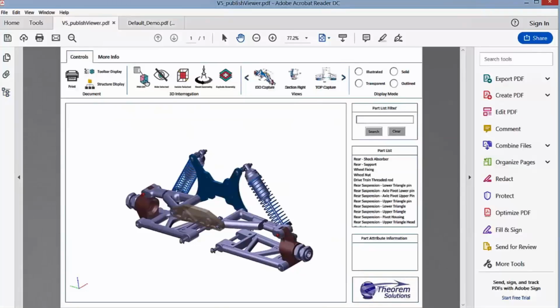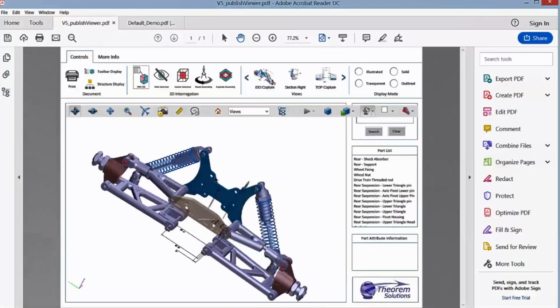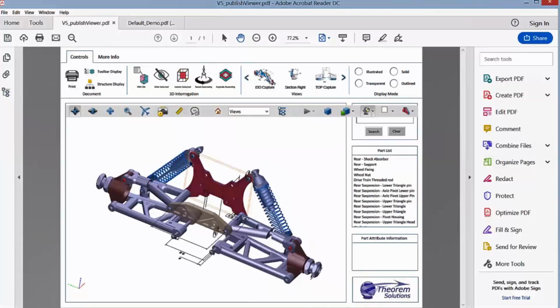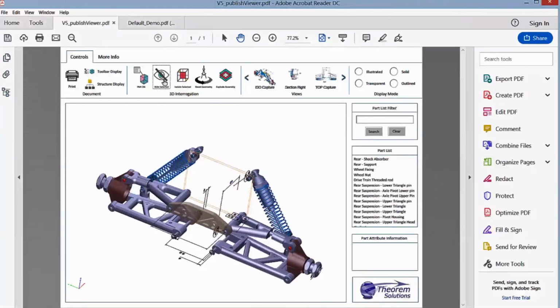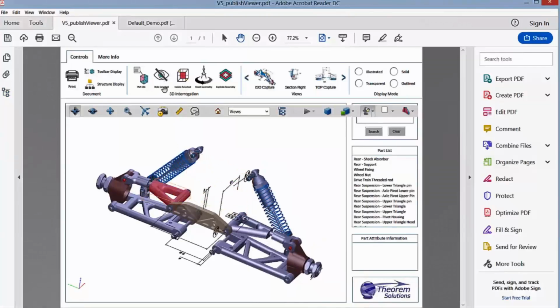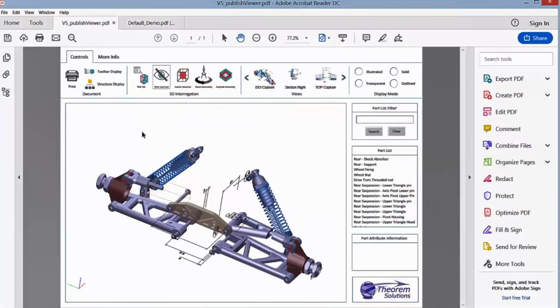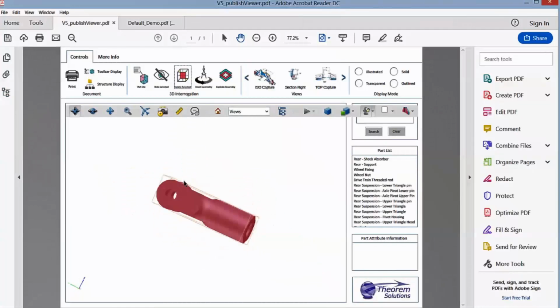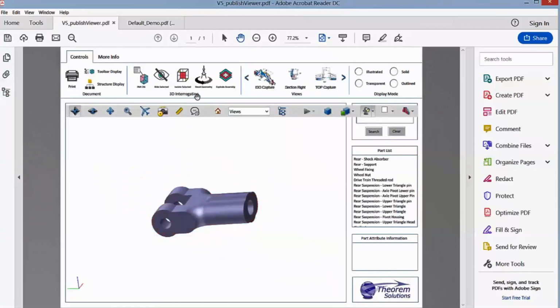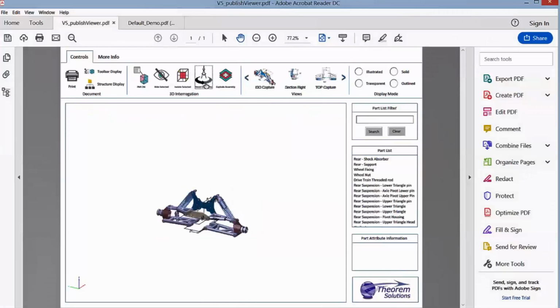So there we've turned PMI on and off. If we select a part of the geometry, we can turn the geometry on and off. So we can hide that and show that. Equally, we can isolate a selected component. So if we wanted to select a component and that's the part we're interested in, by isolating that component, we get rid of the rest. So we're just going to reset it here.